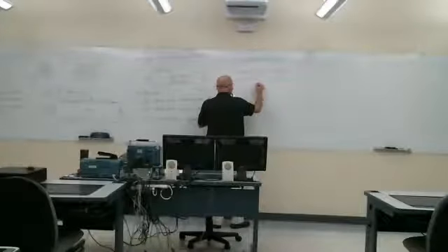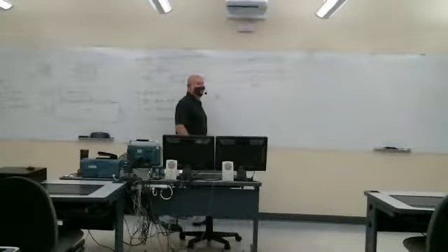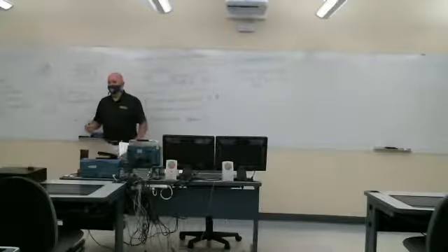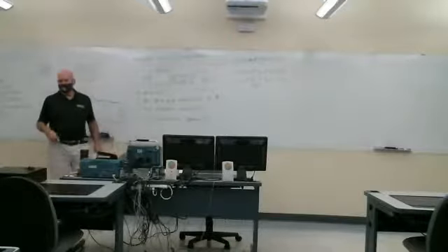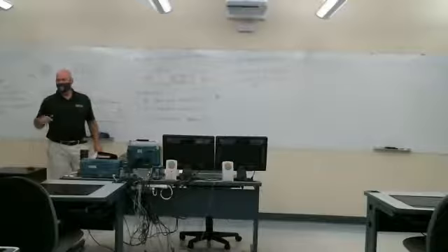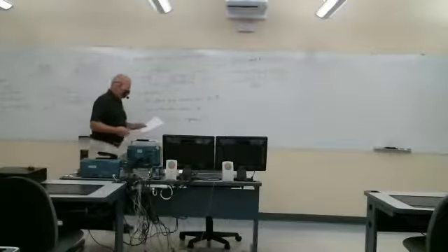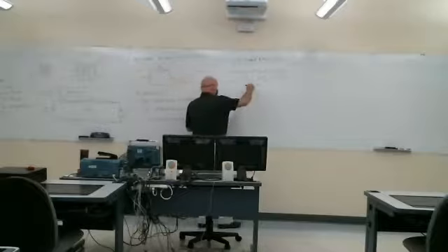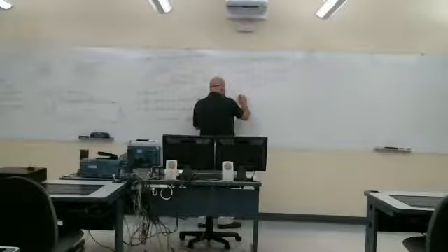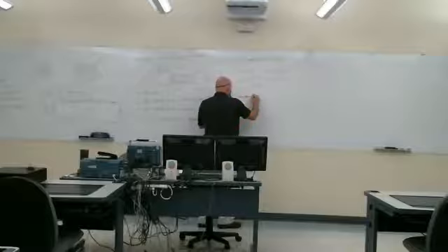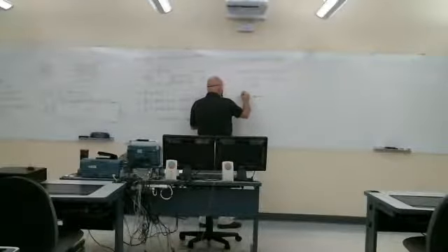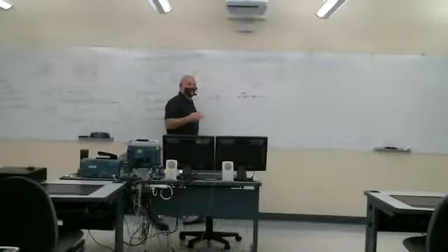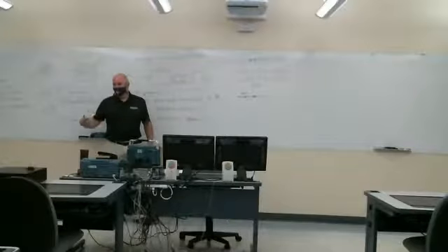Each segment here is of length delta z, and to get the differential equation, we're ultimately going to let delta z go to 0. And then in each segment, we're going to model what's going on in each little segment using a resistance R prime delta Z. R prime is actually resistance per length.